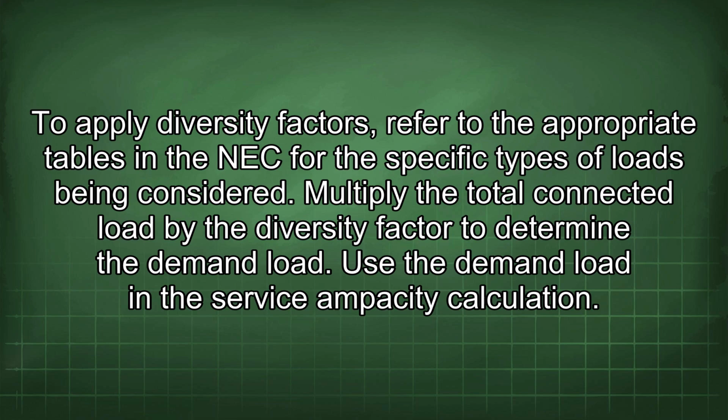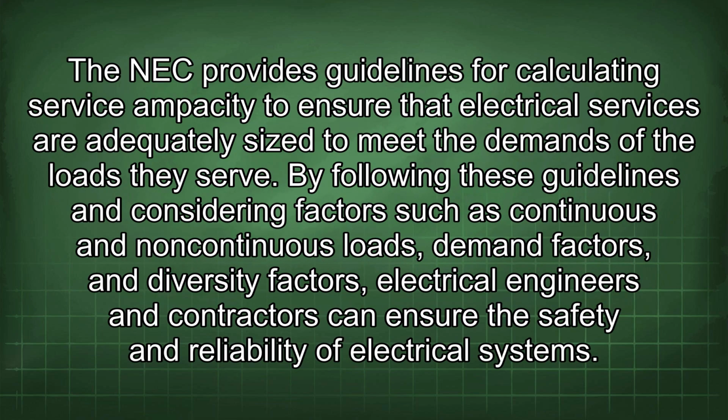To apply diversity factors, refer to the appropriate tables in the NEC for the specific types of loads being considered. Multiply the total connected load by the diversity factor to determine the demand load. Use the demand load in the service ampacity calculation. The NEC provides guidelines for calculating service ampacity to ensure that electrical services are adequately sized to meet the demands of the loads they serve.